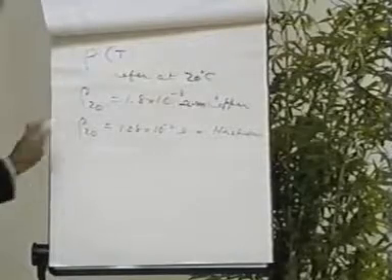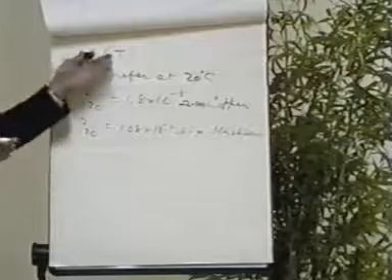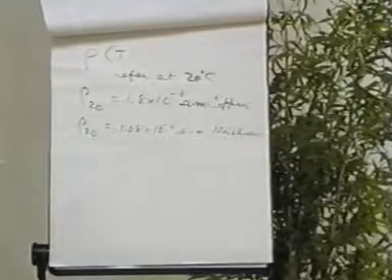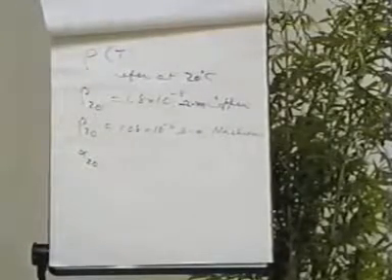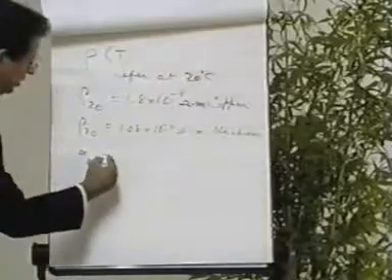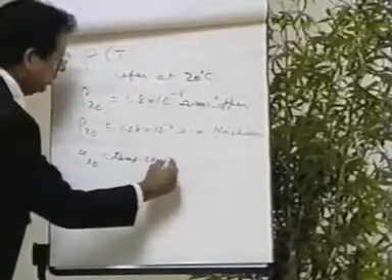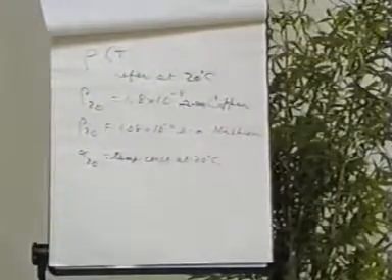Now, let's talk a little bit about this resistivity. The resistivity obviously is a function of temperature, depends upon temperature. And the dependence goes something like this. There's a coefficient called alpha. An alpha at 20 would be the temperature coefficient of the material at 20 degrees C. That'll be our standard basic definition.